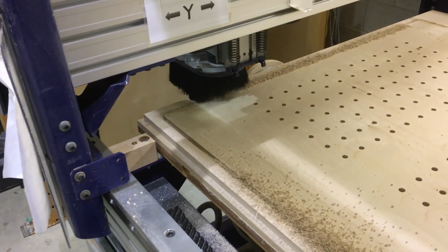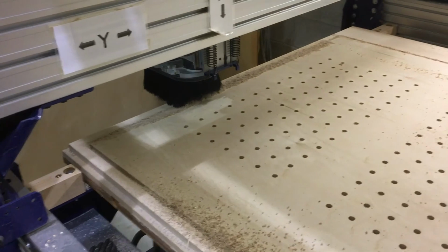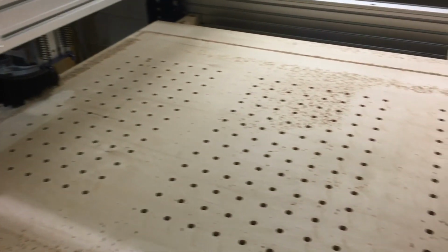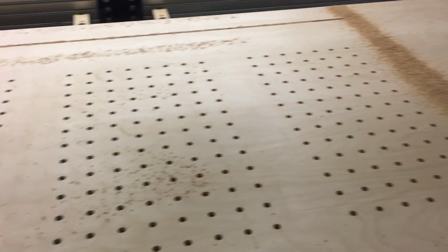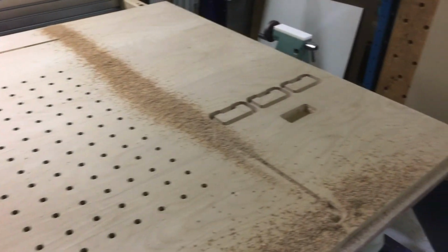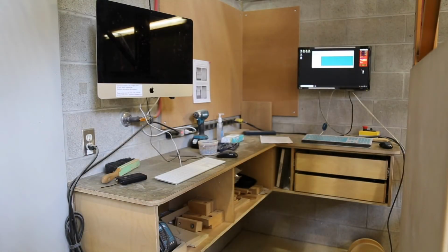Do not leave the machine running unattended unless you have been expressly given approval to do so, as surprises can occur and bits can break. When loading files, transfer them using a USB key to your folder on the CNC router desktop under Student Files prior to running the machine.